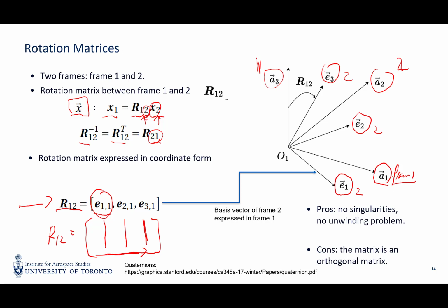But if you use Euler angles and the pitch angle is 90 degrees, then the yaw angle and the roll angle are the same. So you have an infinite number of solutions you can pick for determining how much is your roll angle and how much is your yaw angle. So that is the point where you have numerical issues in terms of controlling. Good.